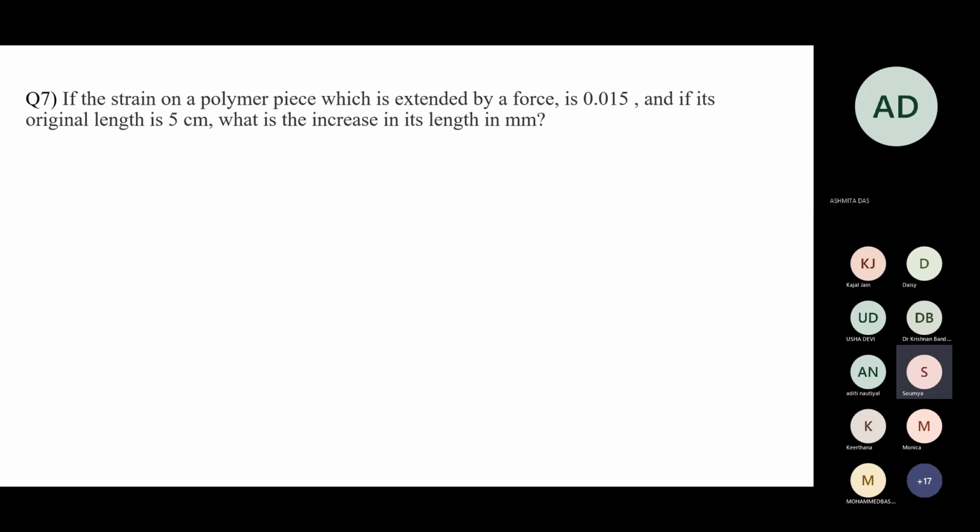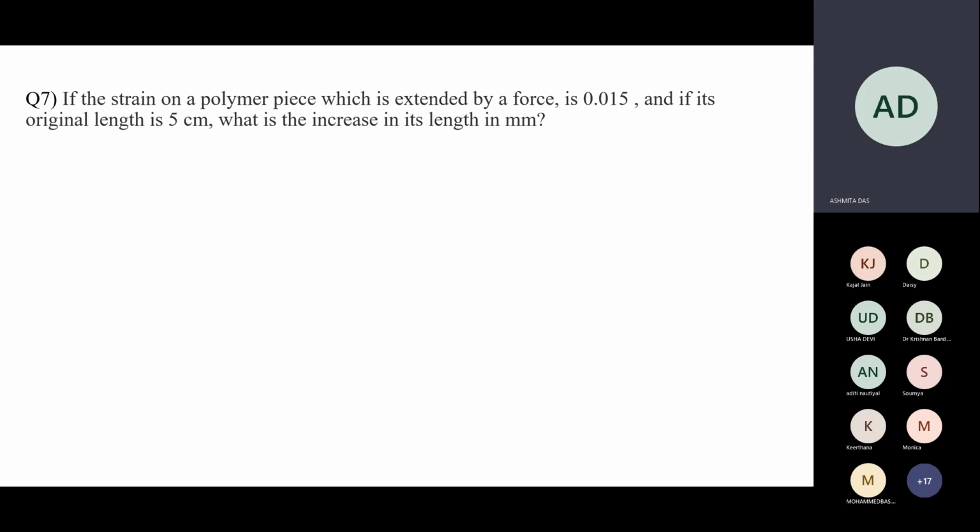Strain is equal to extension by the original length. So extension is 0.3 millimeter and the original length is 250 millimeter. So 0.3 by 250 is 0.0012. Yeah, correct one.